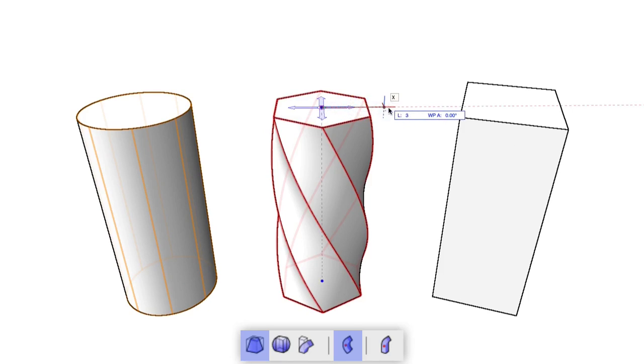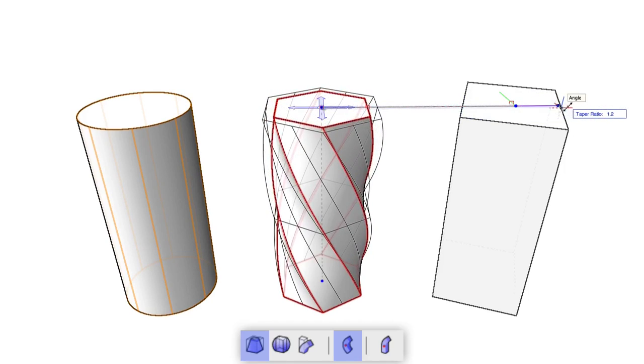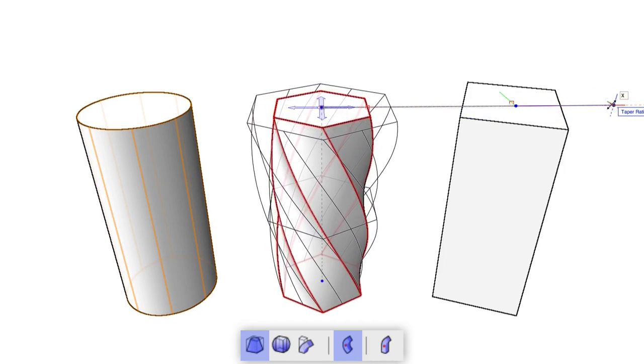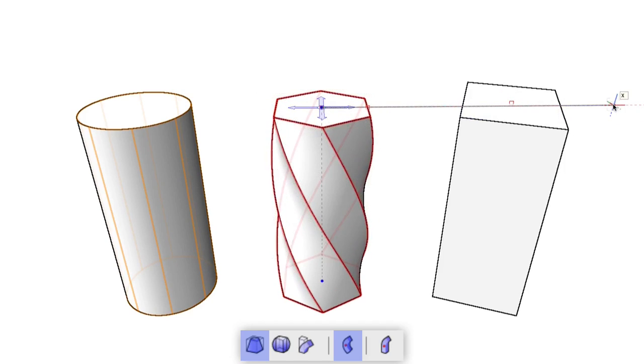The next click will determine the sensitivity of the taper operation. For instance, if we don't click far from the four-way arrow element, the taper changes dramatically with just small movements. If we perform this operation again, but this time set that second to last click far from the arrows, we see that we have much more granular control over how far the object is tapered. This line effectively sets where the minimum and maximum will be for the taper operation. If we drag past the end of that line, the taper will expand in the opposite direction.